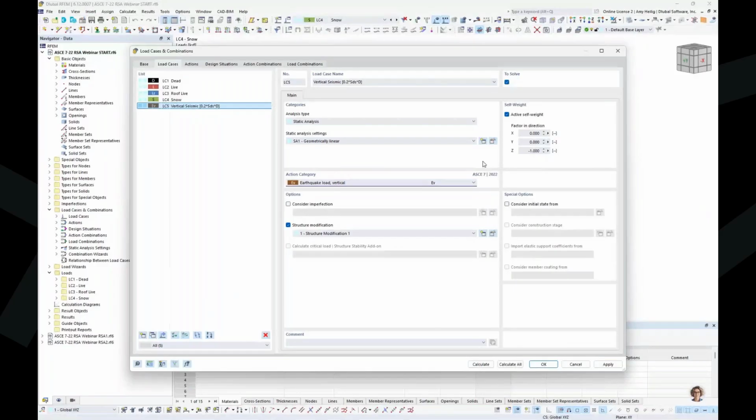But the self-weight was automatically copied over here as well. So this is part of our dead load to consider within this equation, but taking into consideration the 0.2 factor, and for my example today, the SDS is going to equal a value of 0.72. I multiply those by the negative 1 factor for self-weight. This gives us a value of 0.144.